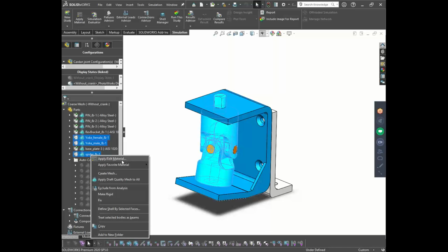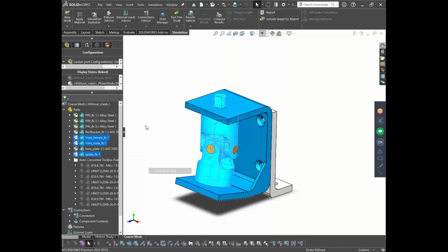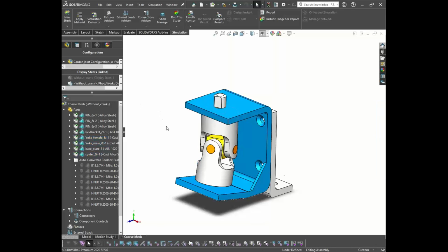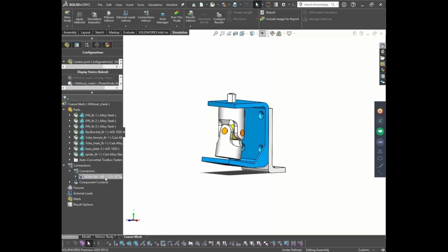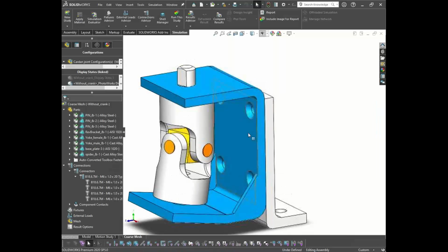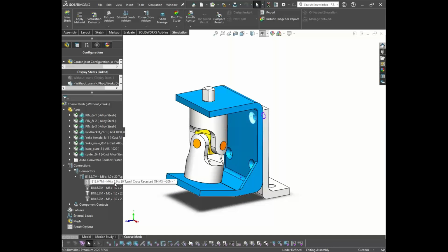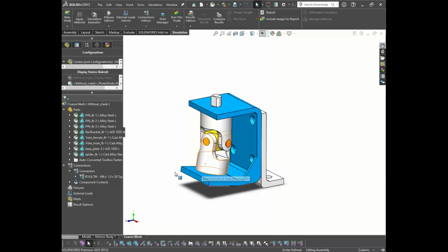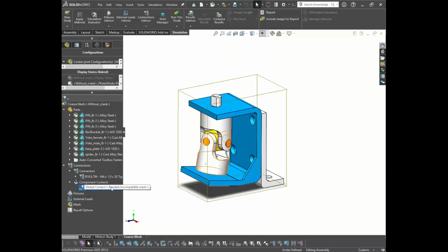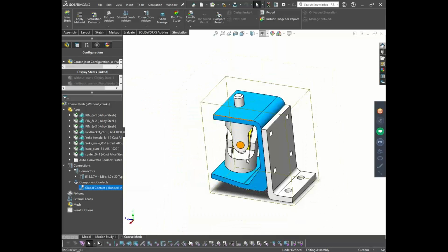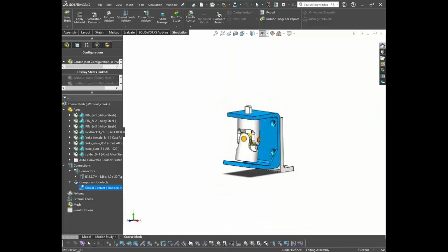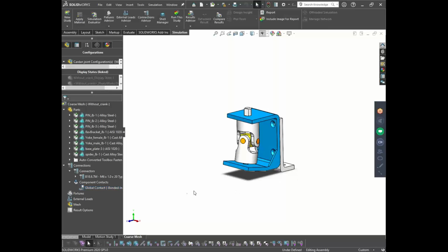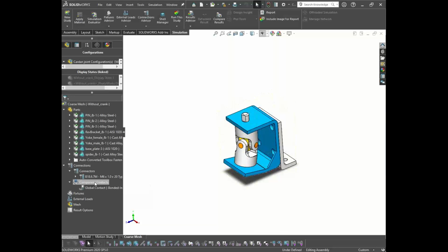For the yoke and the spider, we will be considering cast alloy steel. Our bolts are already converted into the connectors, and they are here. So we need not define any kind of material to them. It will consider the default alloy steel for all the components. Then component contact. So globally it has considered the bonded contact. So whatever the components are in this assembly now, those are glued together. So whatever the results we may get, the assembly will behave in a much stiffer way. But we don't want that. So I'll define new contacts here.